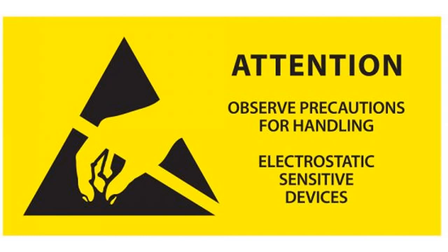Today we will discuss electrostatic discharge, well known as ESD. Whenever an electrically charged object discharges, it produces an ESD, an electrostatic discharge, event. An ESD event can subject an electronic device to thousands of volts and several amperes. High voltage can cause breakdown in a device structure, and high current can cause heat that damages the device.